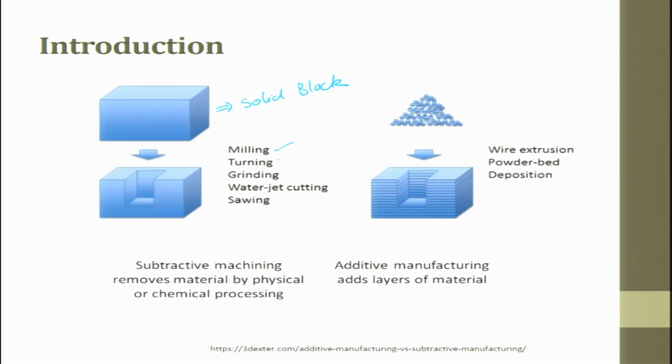We use milling, turning, grinding. If you do not want, you can also do sawing, and you can also try the non-conventional machining processes, where the tool is not harder than the workpiece and the tool is not in contact with the workpiece. So, in the sense of not 100% contact, water jet machining techniques can be used for making such slots.